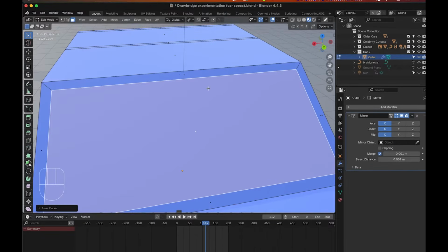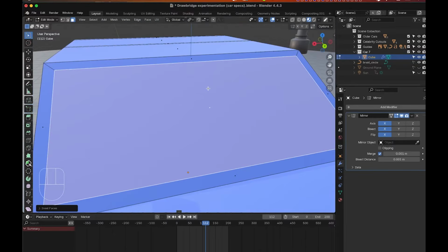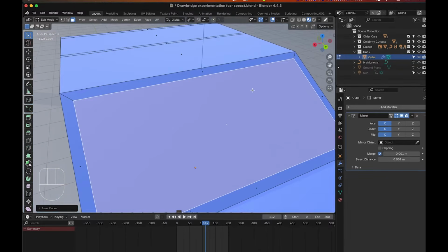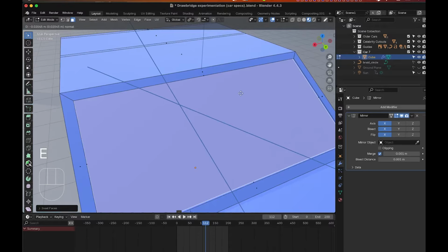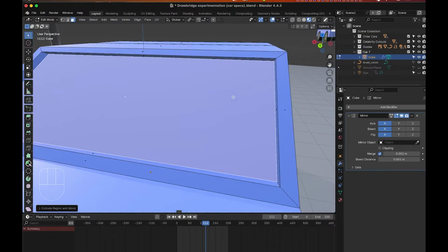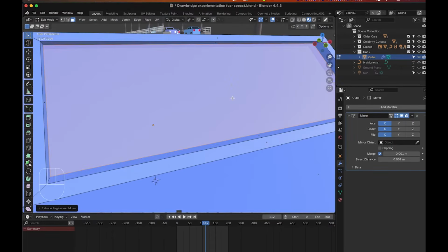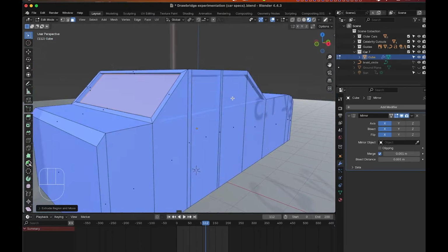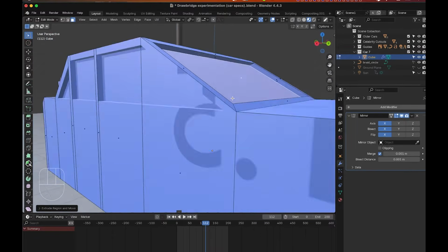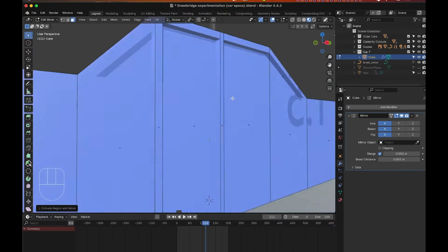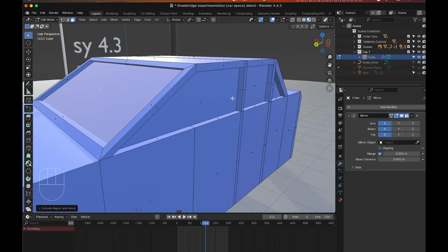And then click where it looks right to you, and then press E to extrude inward. Another extrude, okay, and click. So there we go, and it should be reflected on the back too, because you had both selected. Great, and then if we look back on the other side, those things continued over to the other side because we mirrored it at the beginning.